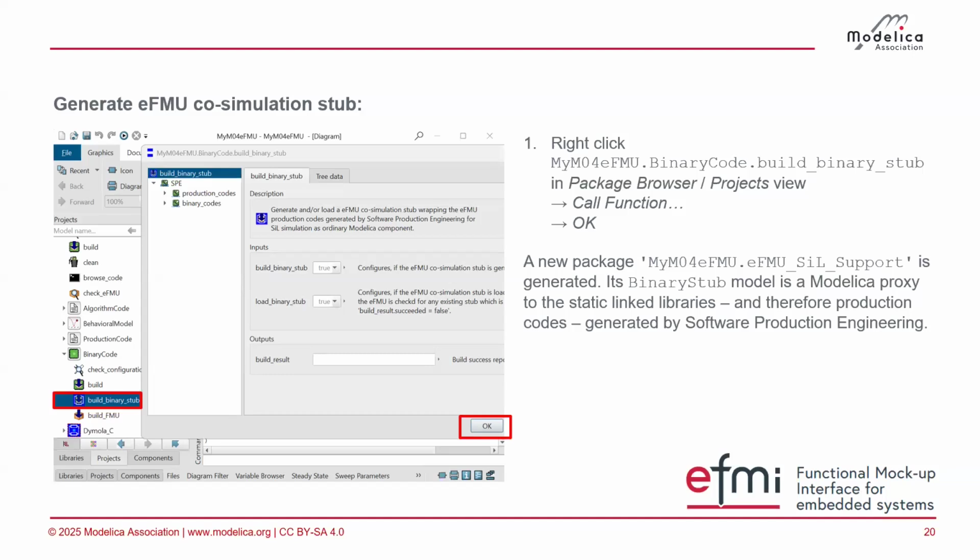And then you want to see, does it do the same? And that's a software-in-the-loop test. So you use the production code that was generated for an embedded system, and you try it with your original test scenarios to see if it does the same.